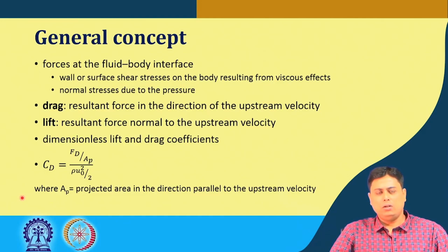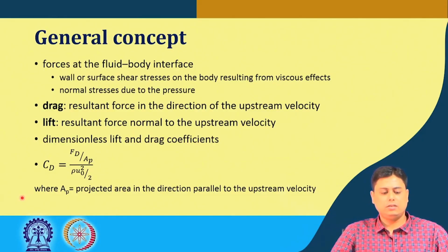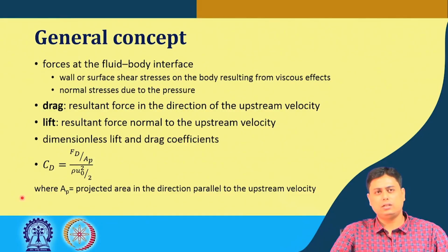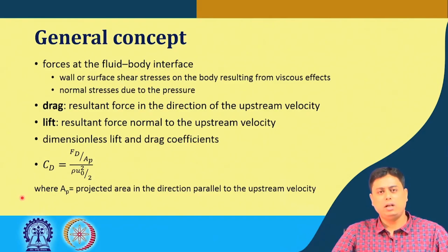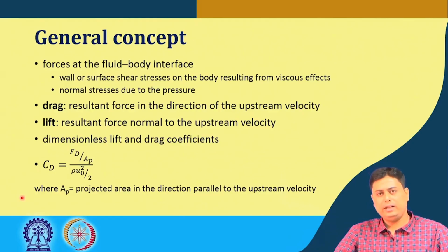Now, to quantify these parameters, there is the concept of dimensionless lift and drag coefficients. Our interest here is the drag coefficient, which, if you remember, we defined as the overall drag force divided by A p times rho u squared by 2, where A p is the projected area in the direction parallel to the upstream velocity.